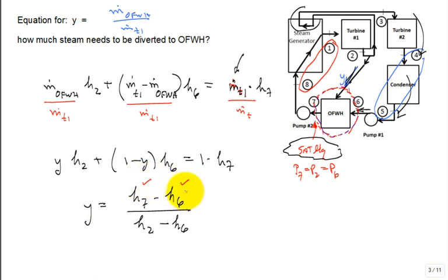Now you think about it for a minute. How about the value of H2? Well, it's what came out of that steam turbine through the first pass. If it's isentropic expansion, conceptually, sure, I'll get H1, then I'll get H2. All right. And then how about H6? How could I get that? Well, you're going to march around, you're going to come out saturated liquid at state 5, and then you're going to add the work of the pump, and you'll have H6.